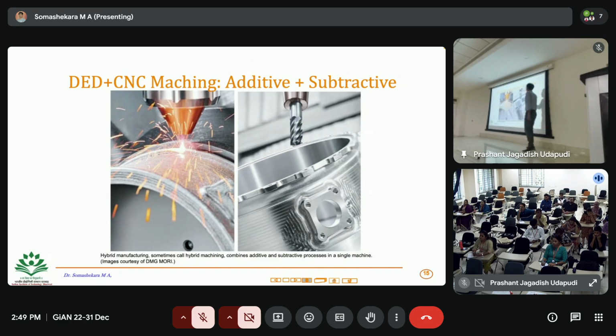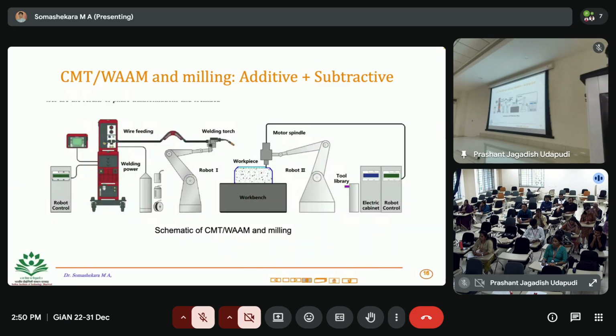So think about it: if I want to make this using a casting or a formative process, how much time or how much tooling would you need versus making the component here? And then think about if you don't use machining for this component, how the surface would look. So you can see that difference in terms of the parts.